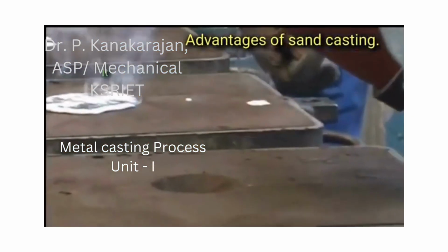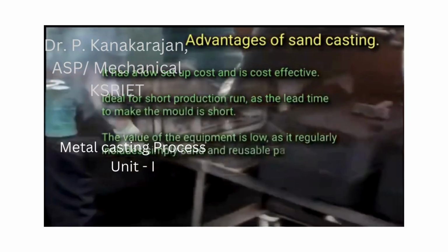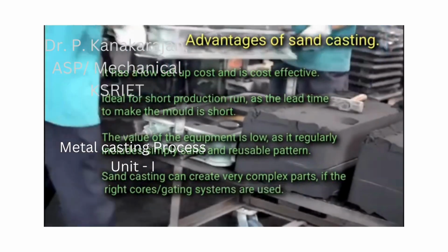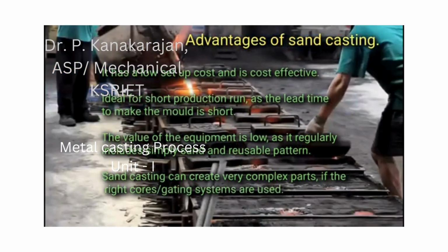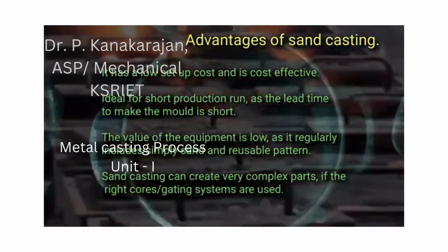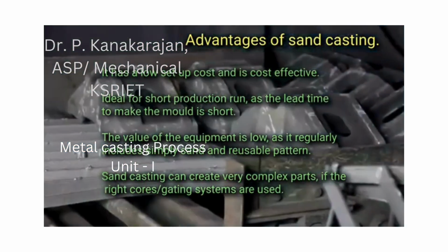Advantages of sand casting. It has a low setup cost and is cost effective. Ideal for short production runs, as the lead time to make the mold is short. The value of the equipment is low, as it regularly includes simply sand and reusable pattern. Sand casting can create very complex parts, if the right cores and gating system are used.